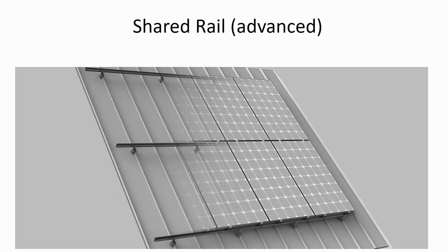So the roof truss or rafters or purlins, that really drives the default orientation of whether or not you mount in portrait or landscape. But then it may be a simple matter of just buying additional rail to enable a landscape mount, which often looks better than a portrait. I like portrait because it's cheap and it's easy, and that's kind of the default for rafters that go up and down the rooftop. But that doesn't mean you can't do other configurations.